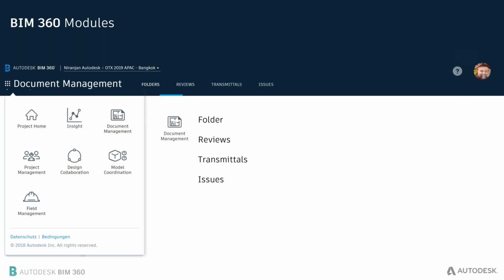So this is mostly for when the design team and others are working on that particular project; they can use just the document management. Now, at certain times, you require collaboration where multiple team members need to work on a file from different locations. You need design collaboration. This is specific to Revit Cloud Worksharing. So what it allows is, you can have the model and enable a worksharing environment, and multiple teams can access it using that. So this is the additional service that we have to offer.